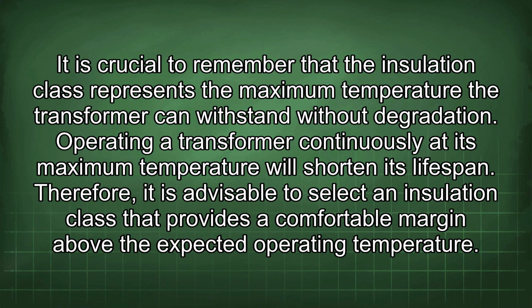It is crucial to remember that the insulation class represents the maximum temperature the transformer can withstand without degradation. Operating a transformer continuously at its maximum temperature will shorten its lifespan. Therefore, it is advisable to select an insulation class that provides a comfortable margin above the expected operating temperature.